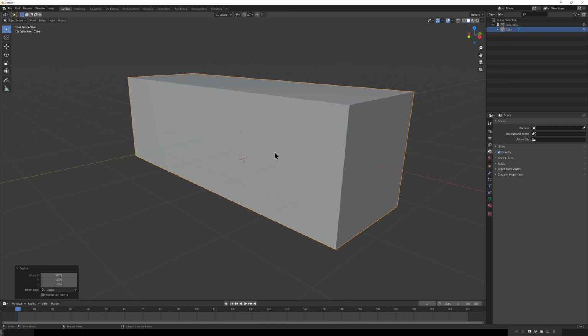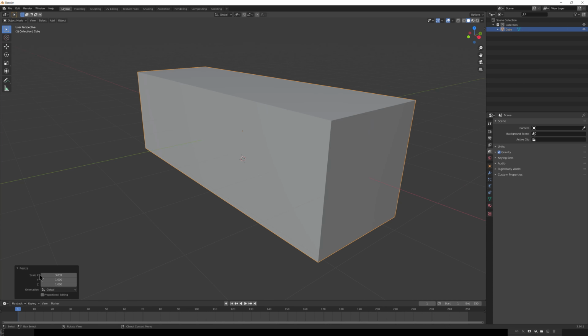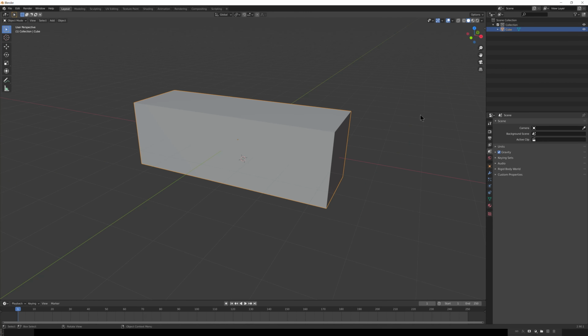What's important is to create it here, get the proportions right when we start, and then we can futz around with getting it to the exact scale we would like inside of Unity later. Here we can see that we've resized this object to roughly a 3:1 ratio. Another thing you want to do though is possibly make sure that ratio is perfect, that is, it snaps exactly at 3. The reason for this is because you might be creating your object and snapping maybe several of these panels next to each other.